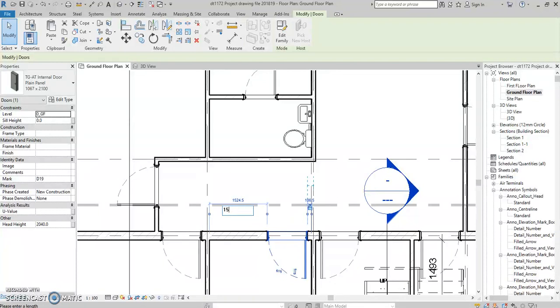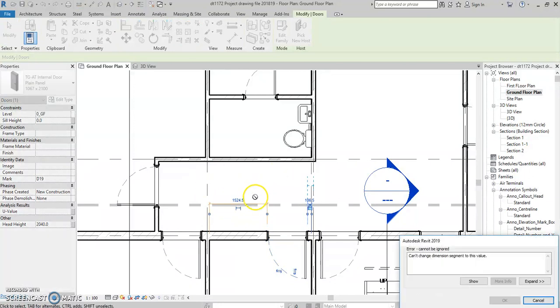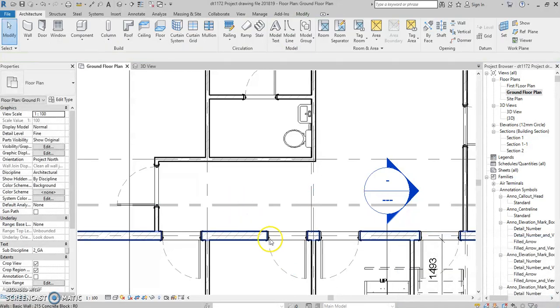So I click on 1500. And more likely for a construction manager, this is what you're going to be doing at the as-built stage. So although it might have been down as 1524, it's actually gone in as 1500. Maybe through agreement, maybe as an error, but it's gone in as 1500 and we need to show that on the as-built drawing.